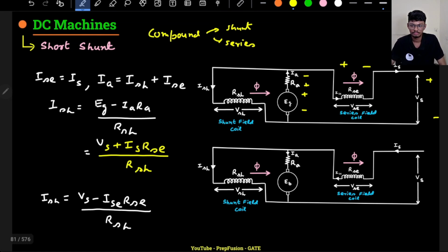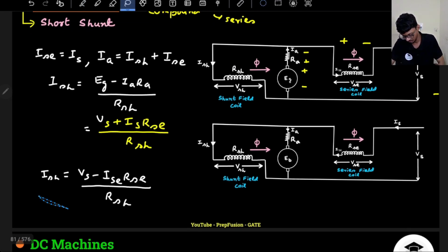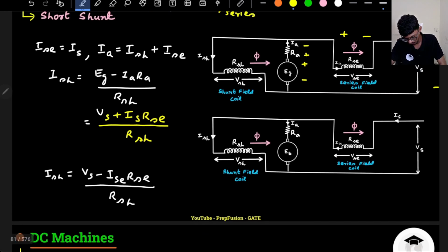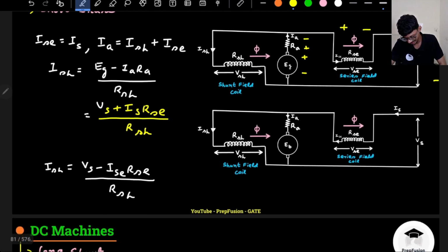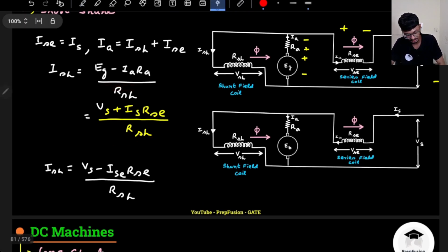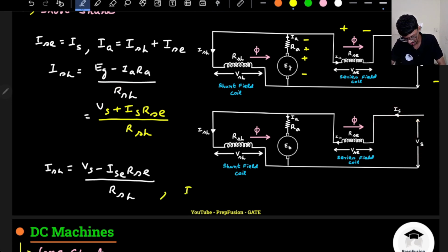Okay, yeah, so that is the thing over here. Now, for a motor, this was for a generator, right? For a motor, just the opposite. This time Vs will supply, so my IS will be equal to IA plus ISH, and again the same thing, my series winding current is the same as the supply current IS, right?